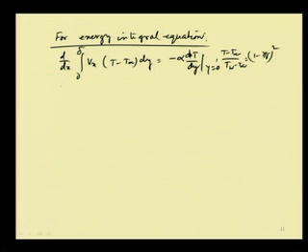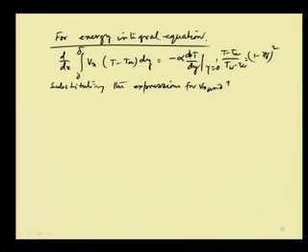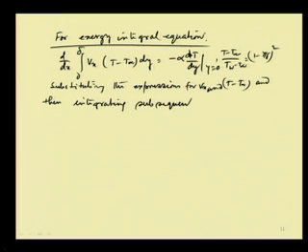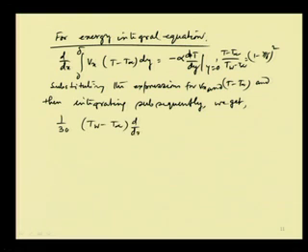Now, once we have that, if we put this expression for velocity, substituting the values of expressions for Vx and T minus T infinity, and then integrating subsequently, we get 1 by 30 (Tw minus T infinity) into d/dx of (u into delta) is equal to 2 alpha into (Tw minus T infinity) by delta. So, this is say equation number 2.